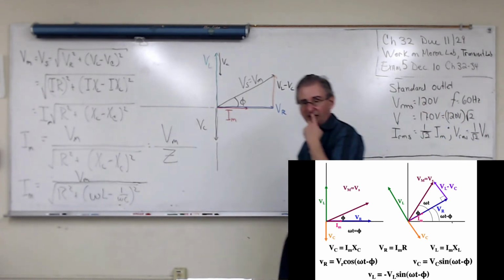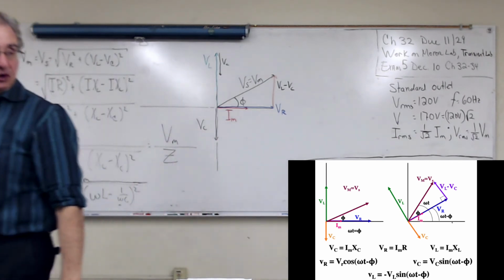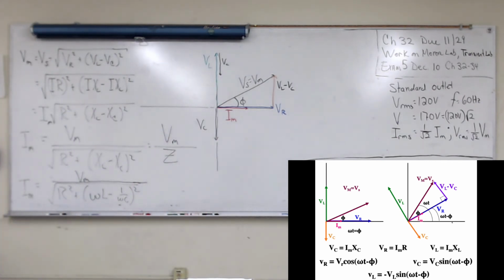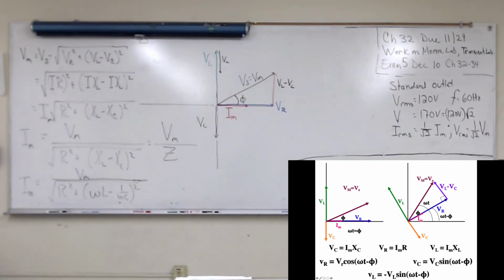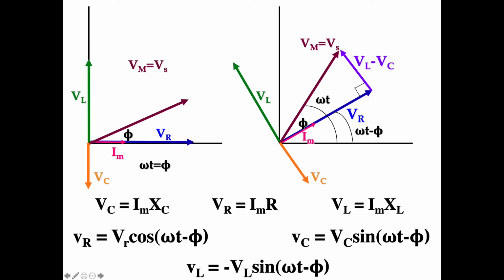Okay, I pretty much know everything about my circuit. And then I've drawn two phasor diagrams. One of them is the one I used to analyze the circuit, the one on the left. And then the one on the right, I drew at some arbitrary angle. I just rotated the whole thing because I think that whole thing rotates with time. I did it some angle omega times time. Phi is always the angle between the power supply voltage and the voltage across the resistor.